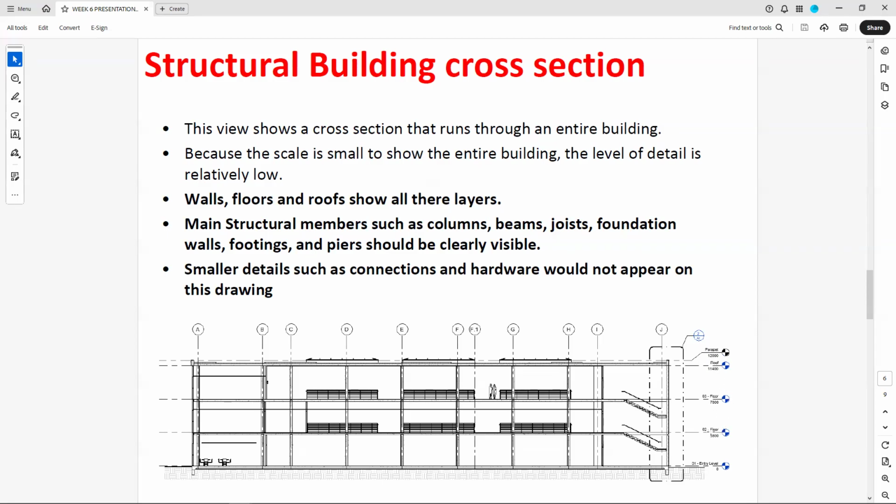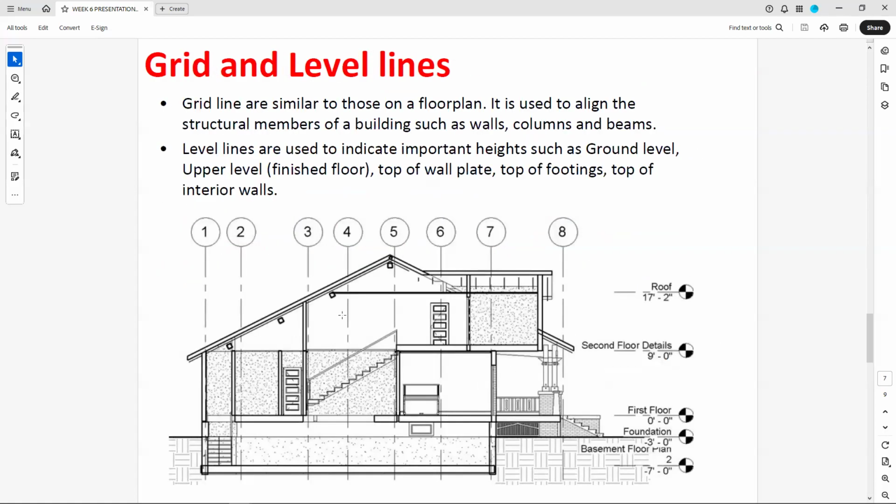And then you label what floor that is. So this will be the 02 floor. This is 01 entry level, 03 floor, and so on. And the roof level, the parapet level. Okay, so you sometimes also add the grid to coincide with the grid that we have placed in our floor plans. And you'd show some details. And where it is cut, that is where you put the thick lines to make your drawing pop out.